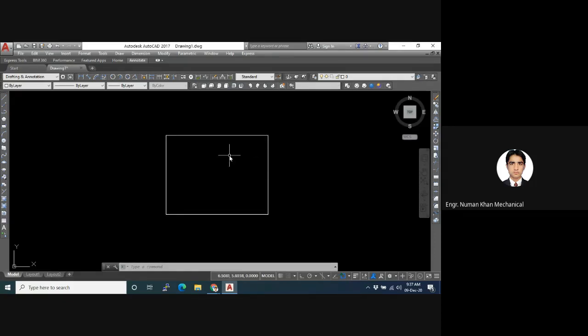If you want to change the properties of this rectangle, if you want to give it inherited properties which will be available in all the rectangles in the current drawing, you can change it. You can chamfer its edges, you can fillet its edges, you can give a line width to the line, you can give it an elevation, or you can give it a thickness.